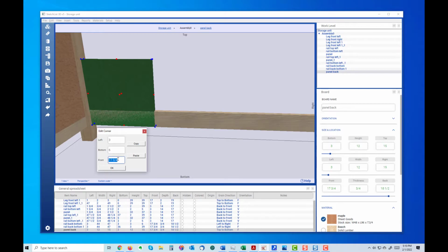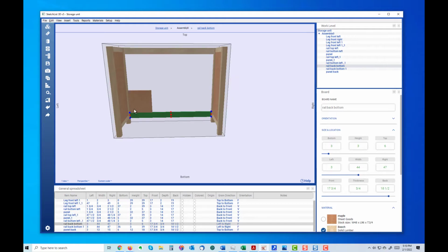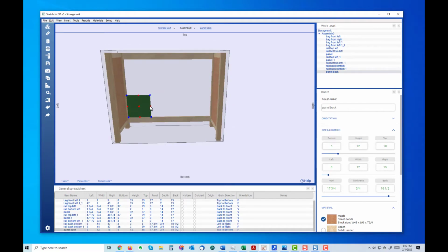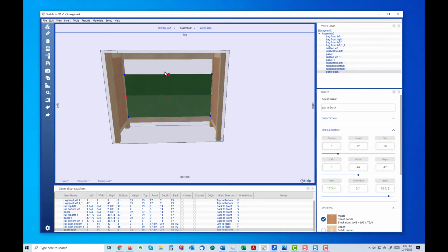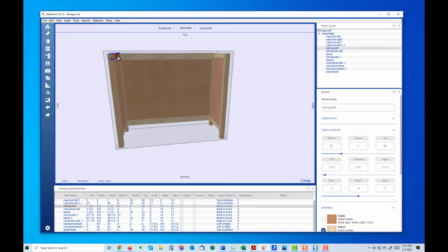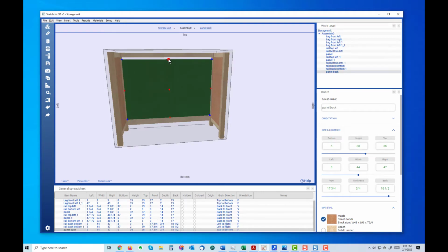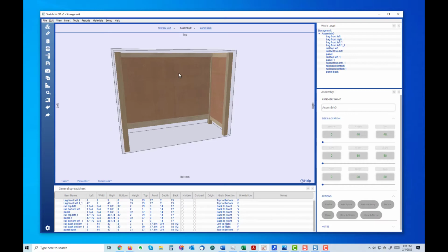So just get out of that, paste that, say OK, and right click, left click the red dot while holding that down and move it over. Right click that red dot, move it up. Oops, I went too far. Notice that that is 2 inches tall. I can right click this and make its height 2 inches. I right click the red dot, make that 2 like that, and again take this Shift key, drag like that.